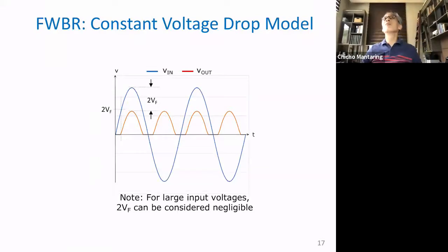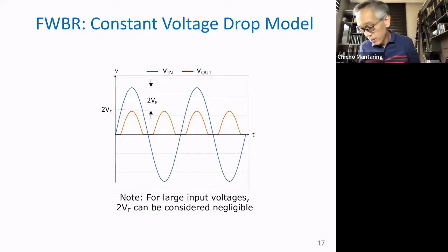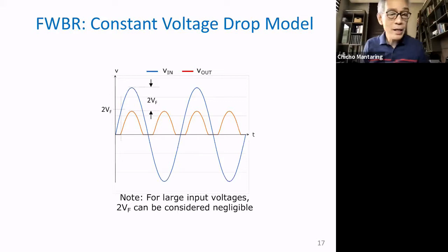So pag tinignan mo, for example, yung mga loob ng charger, no? I don't have one with me right now. But if you open up a charger now and take a look at the inside, there are no more transformers. Actually, ang ginagawa nila is usually yung line voltage mismo, i-rectify na nila using a full wave rectifier, and then they just use a circuit to reduce the voltage. It's called a DC to DC converter. But yeah, you're right, no?